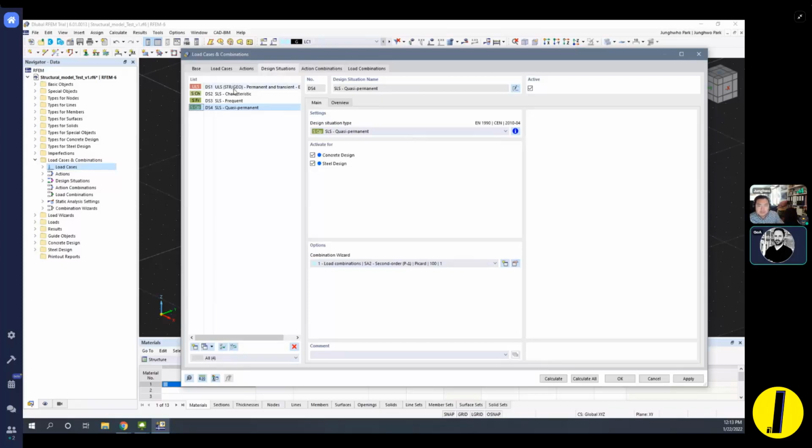So first, ultimate limit state means that all elements should have enough mechanical resistance, and the serviceability limit states are the state where we check the deformation, and we say there's some limited value for deformation. We then say, okay, the deformation of our member should not go over the length divided by 250, and this is the top value for deformation.